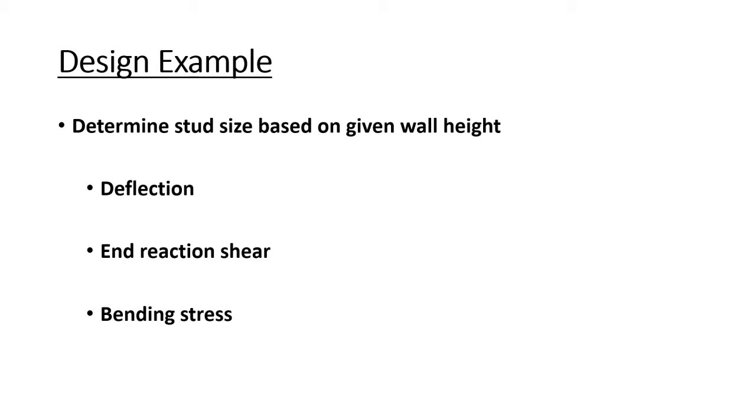Plaster, being more brittle, is therefore limited to L/360. An example of this would be a 10-foot wall is 120 inches, and at L/240 the deflection is limited to 120/240, or 1/2 an inch. The plaster assembly is limited to 120 over 360 or 1/3 of an inch.